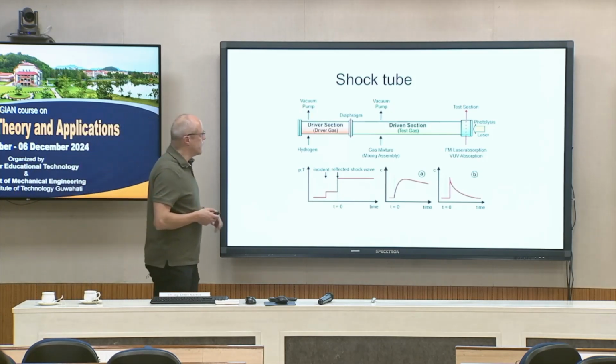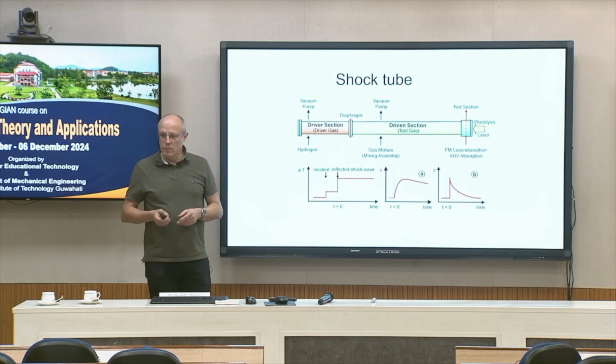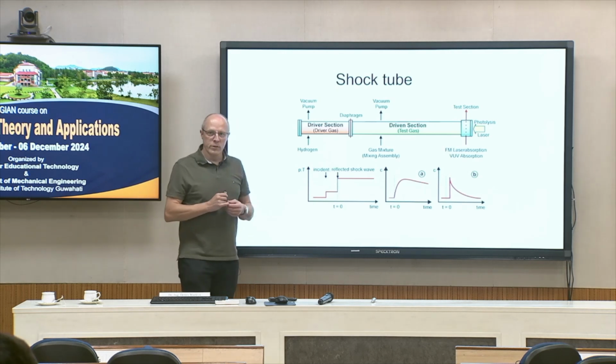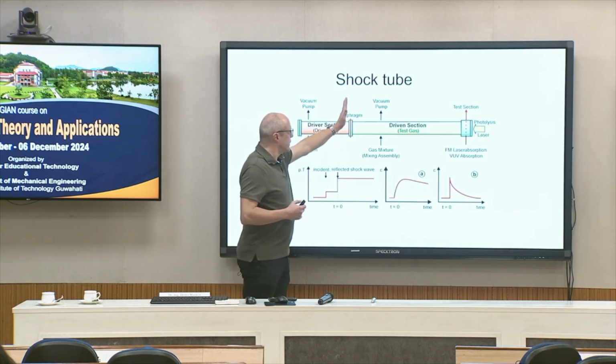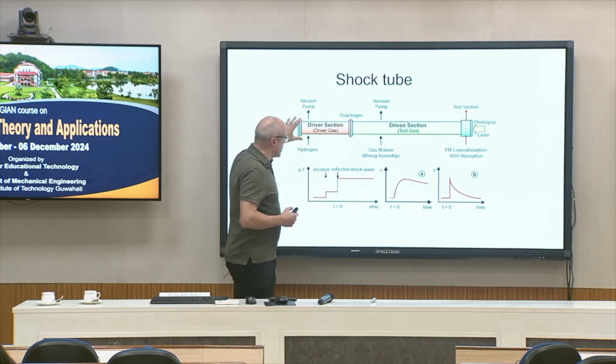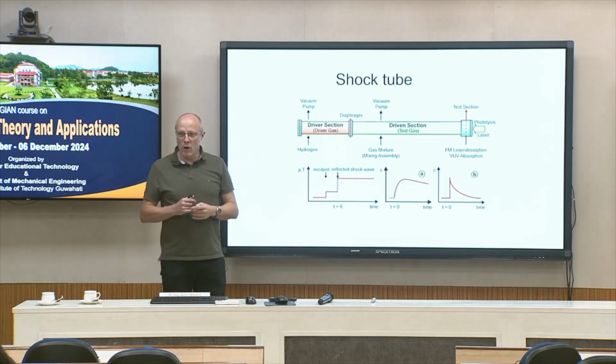So the idea is here we have a driver section with high pressure, and we have a driven section where we also can use lower pressures, lower pressure than ambient pressure. And we have a diaphragm which is separating these two sections and can be opened in a controlled way. And after this diaphragm has opened, the high pressure gas expands into the lower pressure region.